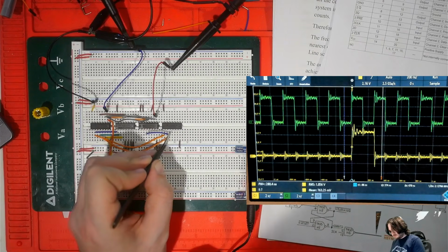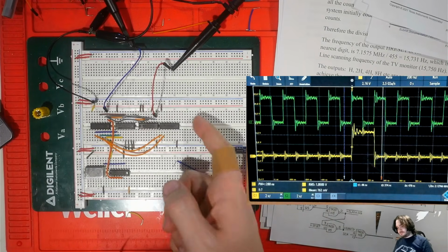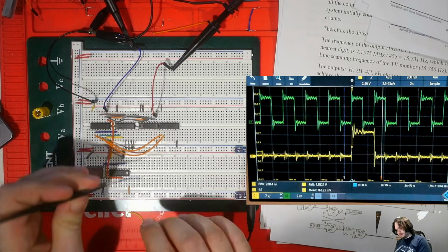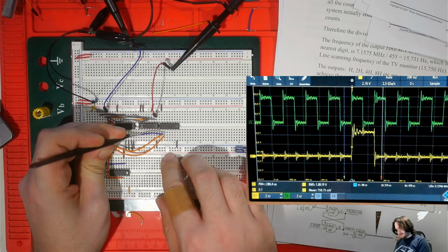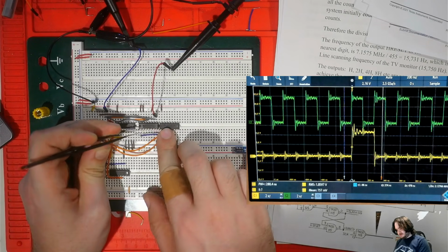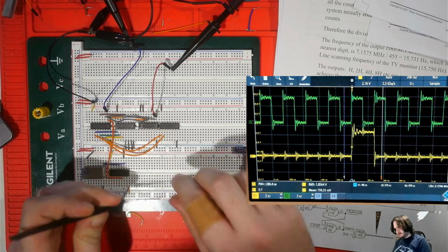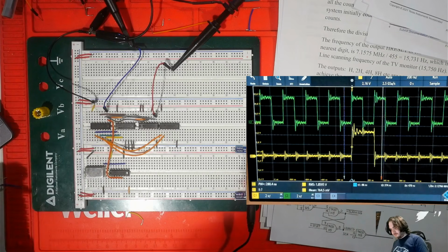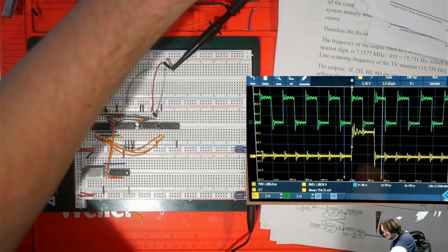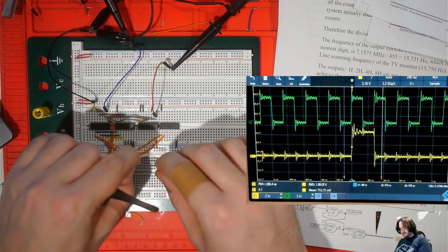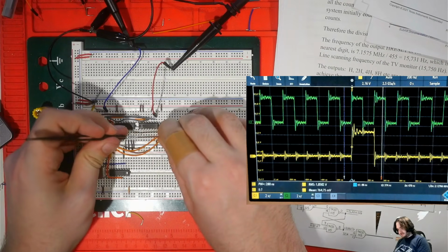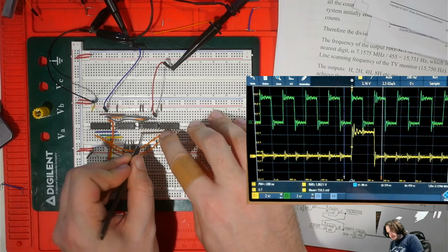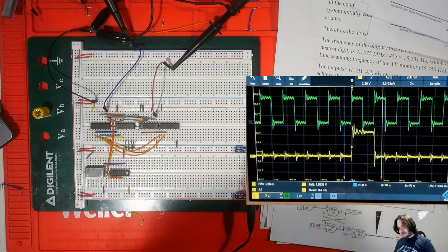No, I don't think so. I've shifted over this by 1 and skipped over that just to save your time. My wire for reaching this is not quite the right one as I had rehearsed. Now the brown wire from this kit, the long one, is the one that should reach 10 spaces, so we wanted to connect the output of this NAND to the clear input on this side.